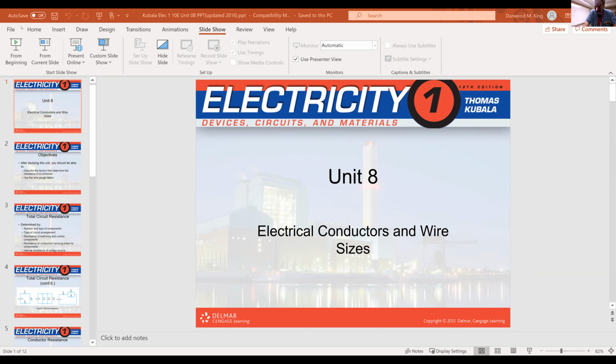Or problems with circuit breakers, that can give you resistance in your control area. And then the resistance of the conductors carrying power to the components. That's one that we're going to get into today, is that the wires itself that go from your switch or so on out to the load, the resistance of those wires, it starts to matter when you go hundreds of feet, like on hog farms, places like that Jamie deals with all the time.